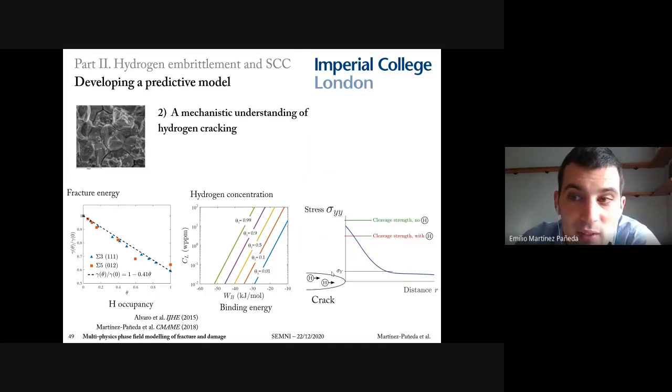And if we couple these two ingredients with our enriched description of crack tip stresses, then we see quantitatively that the stresses are not high enough to trigger brittle failure in the absence of hydrogen. That is why metals fail in a ductile manner. But when you take the role of hydrogen into account, then you lower the cleavage strength sufficiently such that your dislocation hardening and enhanced stresses are high enough to hit the cleavage or grain boundary strength, and brittle fracture occurs. So we have learned what happens, or so we think, and if we incorporate this physical effect into a model, we can capture this ductile to brittle transition without any arbitrary decisions or fitting parameters.